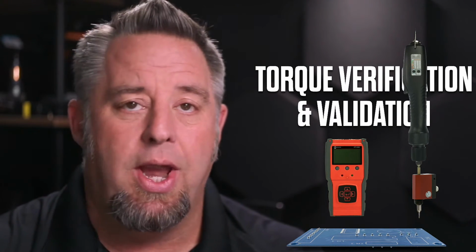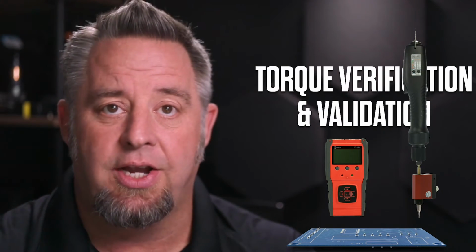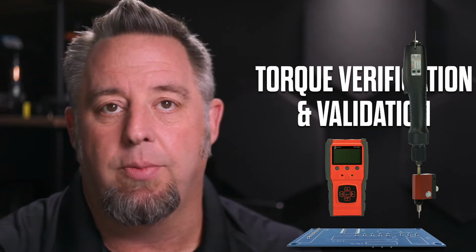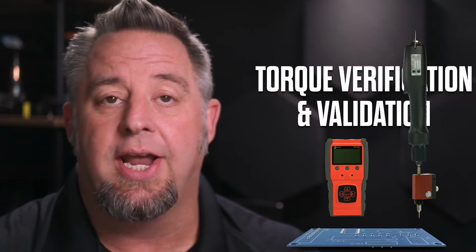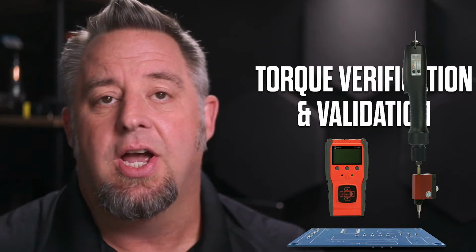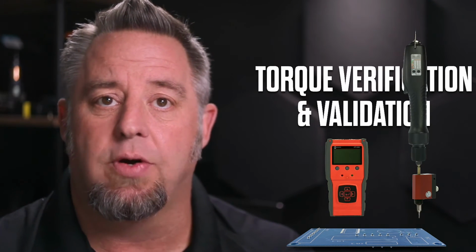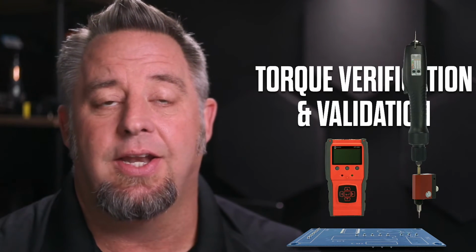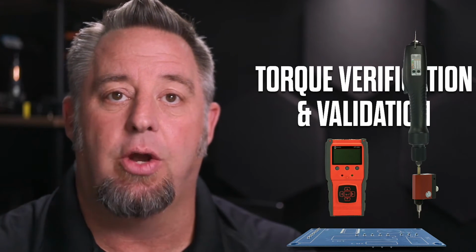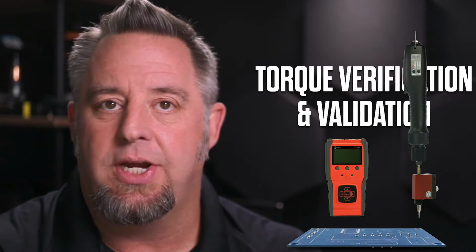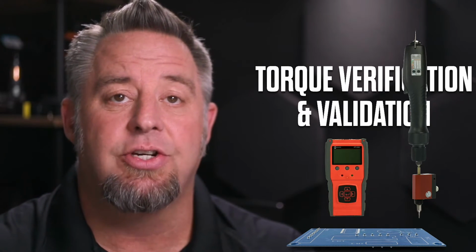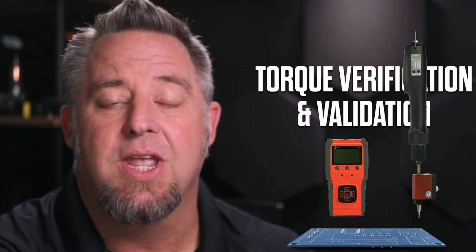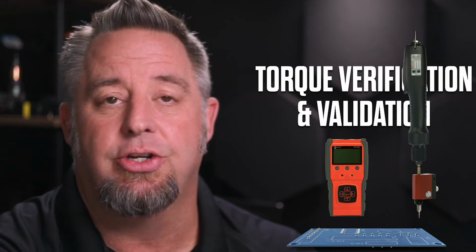Another way we can do the validation is by using a torque analyzer and periodically coming through and testing the tools on the line to make sure that they are performing repeatably on the torque analyzer. So there is a little bit of difference there. When we use the rotary sensor, we are actually getting the torque value that we are getting on our part. When we use a torque analyzer, we are getting a torque reading that we are double checking to make sure that that is repeatable. But the joint characteristics between the rundown adapter that we may be using on the analyzer versus the actual part may be slightly different. And so that's a consideration to think of. So those are the ways that we can do some testing during the application.